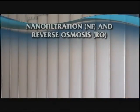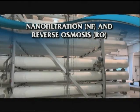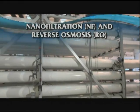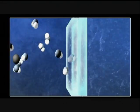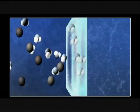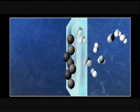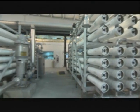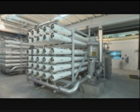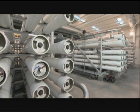To meet that challenge, some utilities are using semi-permeable desalination membranes, nanofiltration, and reverse osmosis processes. These membranes don't have pores. Instead, the water diffuses across the molecular structure of the membranes. Most molecules of suspended or dissolved substances can't pass through the membrane. These processes are more powerful but more expensive to operate. They require more pre-treatment and higher operating pressures.